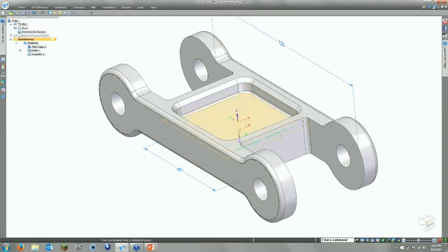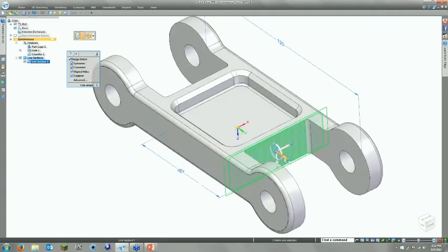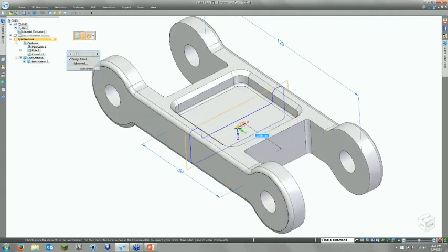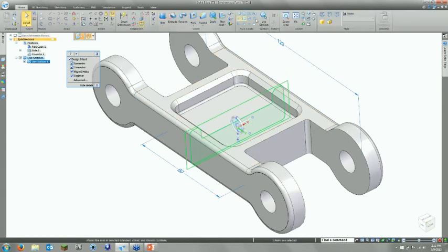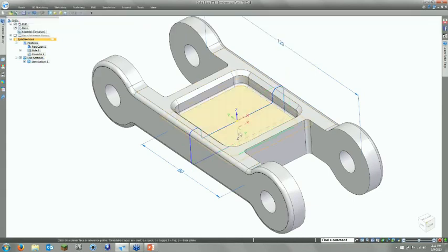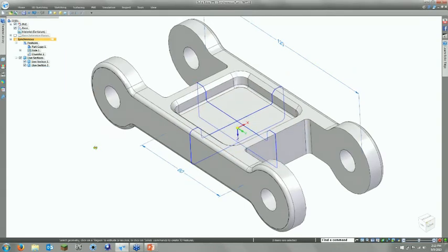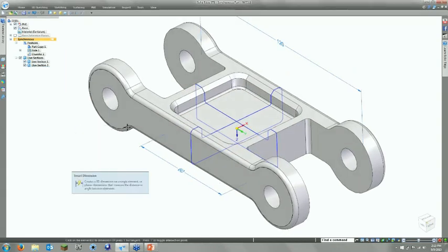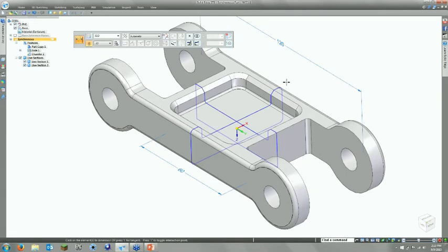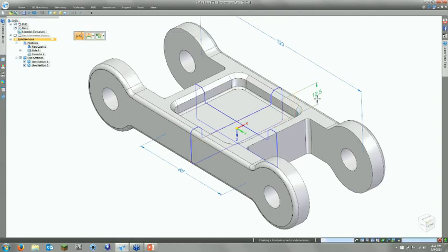It's called a live section. It allows you to put a piece of geometry, which is a sketch, anywhere you want along the part. I can actually create it on reference planes. I could drag it through geometry. So let's create one in the opposite direction as well. So there's my two live sections. So what can I do with that? Again, like I placed the dimension on the overall hole location, I'm going to say I need to, first off, change the thickness of this. So let me go ahead and drag that out. And let's go with 8, because I think I want an 8 wall thickness.